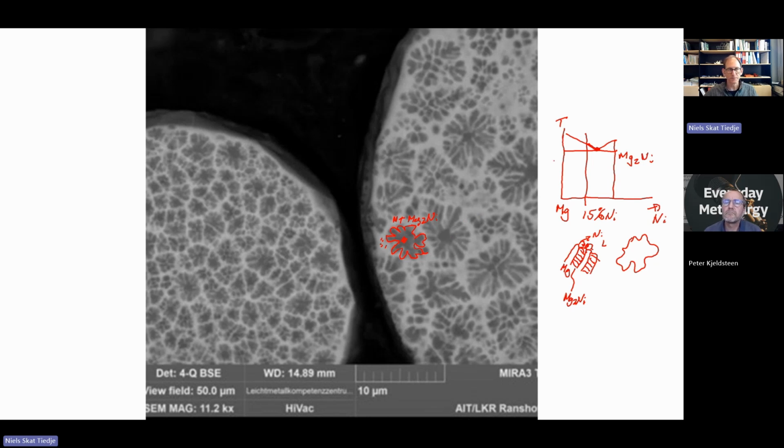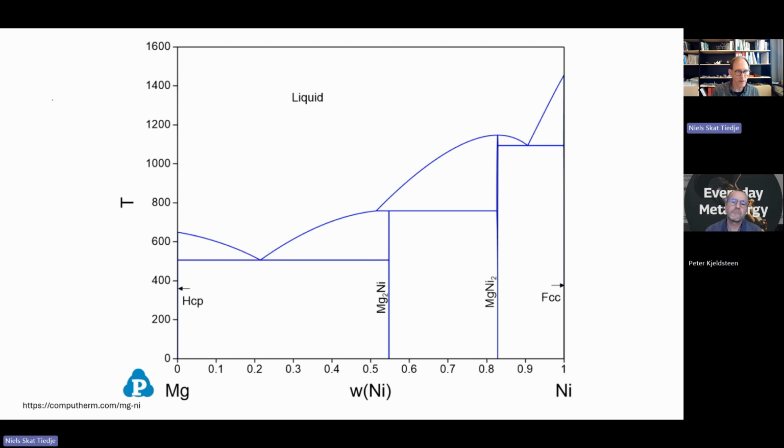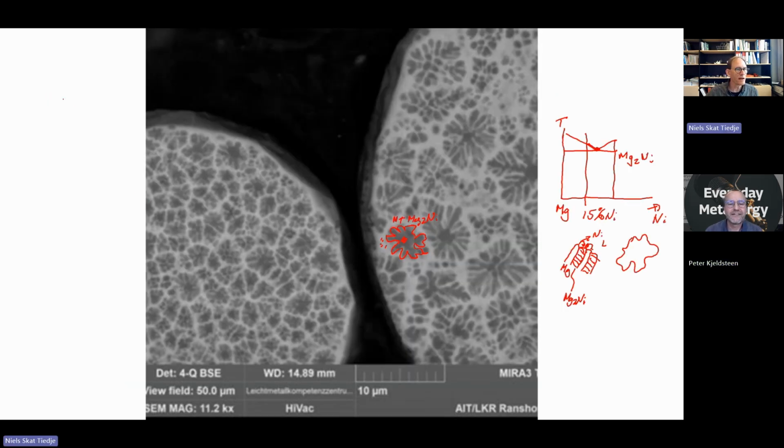But we also have to remember, I will draw on the other side. Sorry, it's very lively, this. But let's assume this is the surface of my sample. And I have an electron beam coming down here. Yeah. The electron beam analyzes a volume below the surface. Penetrates. Yeah. So if I have a dendrite arm here, I will, of course, see the dendrite arm, but I will also see the material below it. Yeah. If my dendrite arm is twice that thickness, I will get a slightly variation in color. And I do not know where I section these. I think that would be my main reason for seeing that difference in shade. It's a pretty fair explanation.